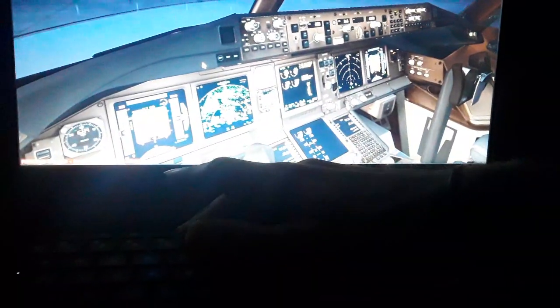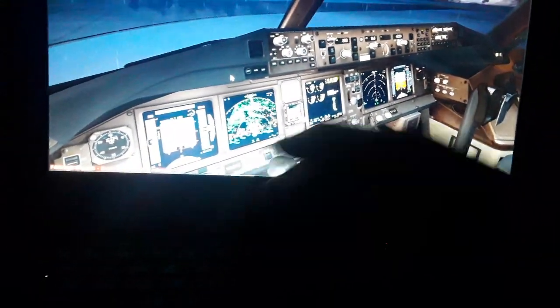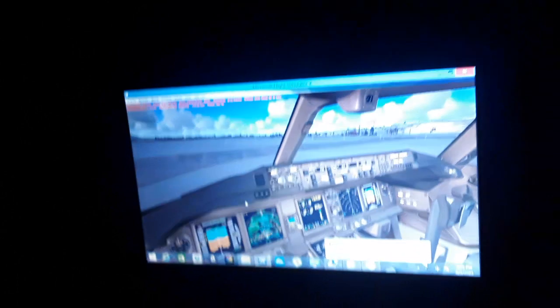We have the attitude indicator with the pitch ladder in degrees and the bank angle in degrees, the ILS localizer, the horizontal localizer and the vertical glide slope, the source of the flight director crossbars for manual guidance of the aircraft, and the autopilot crossbars for automatic guidance of the aircraft. You can see the angle of attack of the aircraft as it flies. Also the flight mode annunciator with the autopilot and the autothrottle, later on in vertical navigation mode.